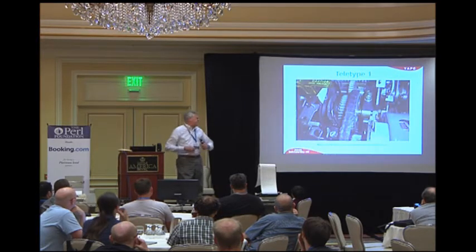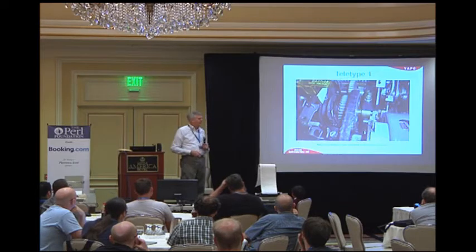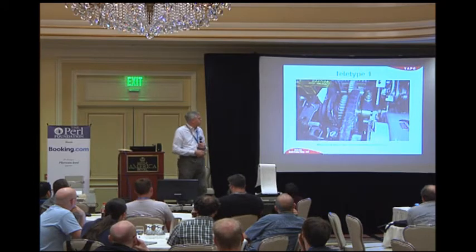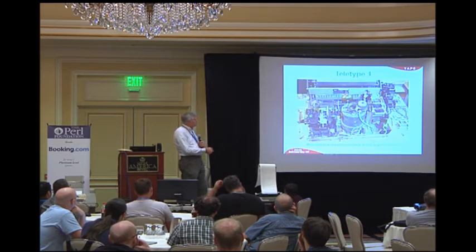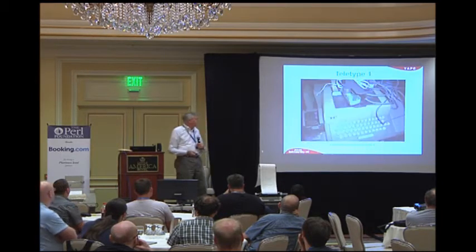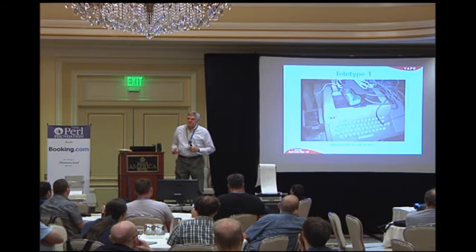As you go through it, you're just looking for anything that's bad. And in this particular machine, you can see cracks on this belt. So that belt's going to have to be changed. And on this one, you notice there's a tooth missing on that gear when I pulled that out. So the question is, where do you get parts? Well, it pays to have a spare parts machine.